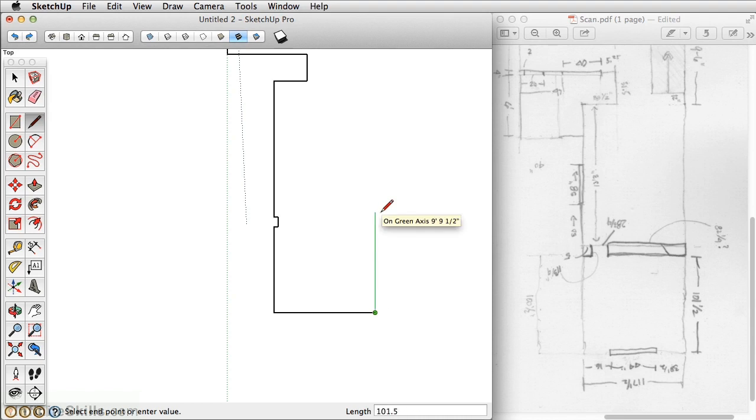And there is actually a little bit of a difference in the baseboards here. And I probably wouldn't have written that down. I would have just rounded this number up. But because this is the kitchen and it's such a small area, and later in the chapters, we're going to focus on creating the cabinets and putting in appliances, it's really crucial that we have that measurement exact because I want to make sure the appliances that I want are actually going to fit in there. Let's put this again at 101.5. And this opening here at 82.25.